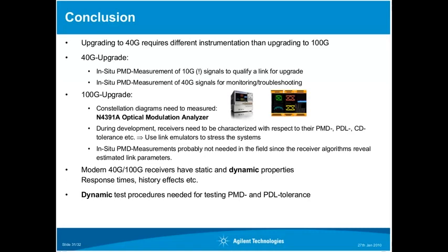Once you have the PMD coefficient, you have the full information about the first and second order statistics. So measuring the effective DGD is just a vehicle to get to the PMD coefficient. It is also a way to measure your momentary distortions, so it might be interesting to be able to measure second order there. At the moment this is not implemented yet. The effective DGD more or less focuses on first order distortions to get to the PMD coefficient in the end.